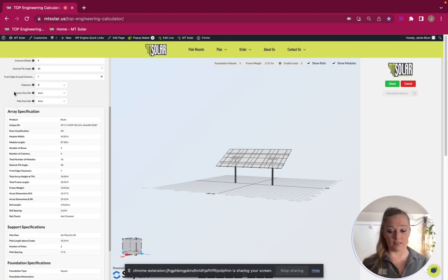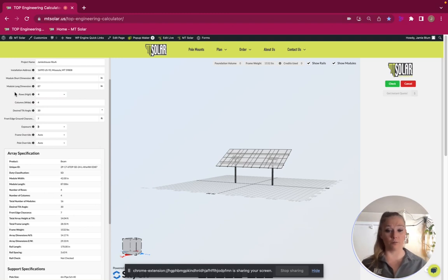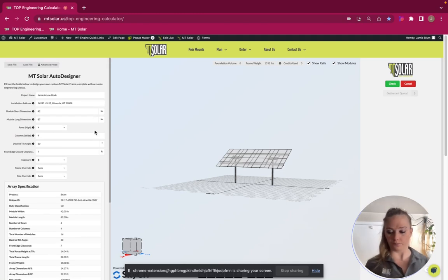And with this design, a complementary foundation will be provided with the structural calculations. This design is to use soil class 4, which is sand, and a 48 by 48 inch square concrete foundation. If you wish to have a different soil class considered for the foundation design or a different size, a full geotech report will be needed, at which point it makes more sense for you to work with a geotech engineer or local PE to design that foundation, and that'll keep your costs down as well.